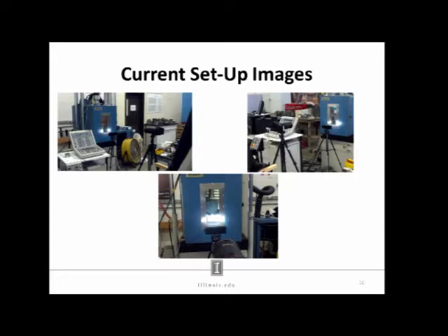One thing that I do want to note, though, is that we did see some issues initially. If you do use an LED light source coming from outside, if you're using loading arms for a DCT specimen, you can get a little bit of a reflection there. And you have to be careful because, well, not reflections, shadows. If you get a shadow there, obviously you're going to have a problem with the pixel intensities that you have.